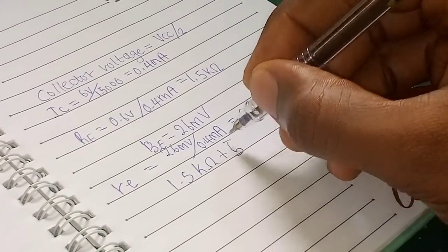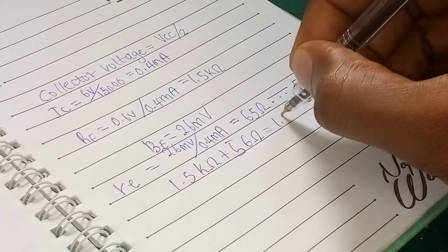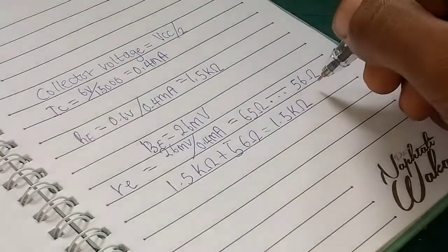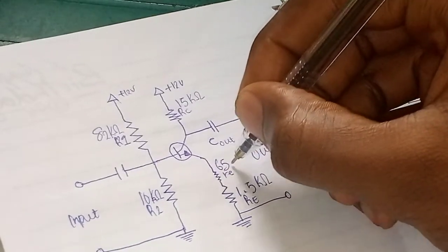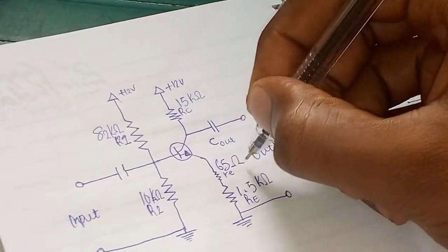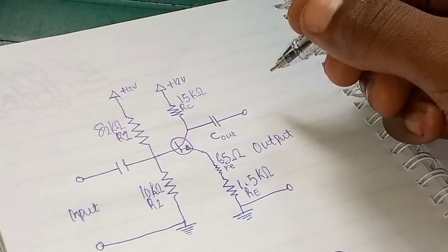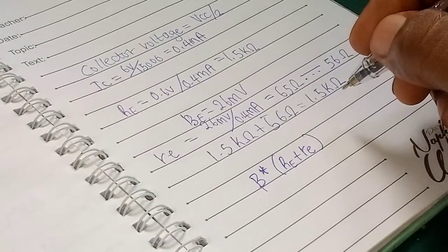Now that we have gotten the biasing resistors for the base, emitter and collector of the transistor, I think it is time we calculate the impedance of the amplifier. The input impedance of the amplifier is equal to the voltage divider resistors in parallel at the base of the transistor, which is in parallel with the emitter resistor, due to factors concerning the beta of a particular transistor.